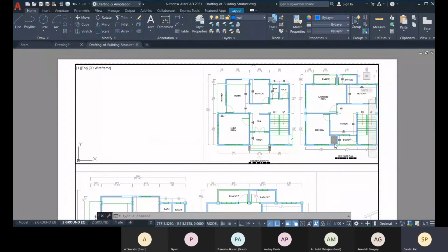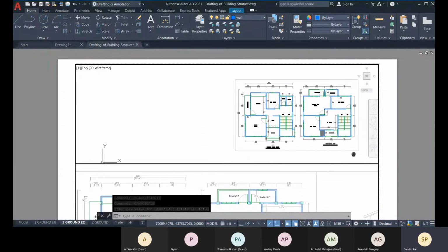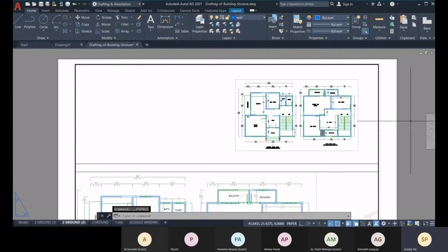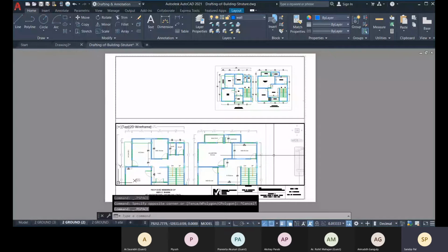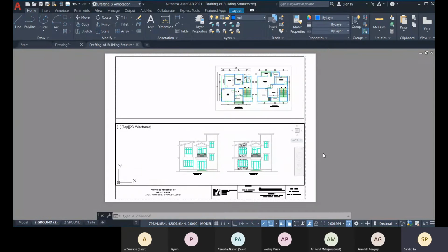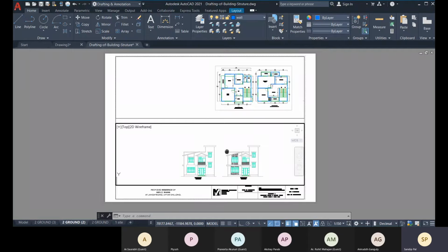This is selected right now, and here you go to this 1 is to 150. Yes, this is right now fit, and you can place it a bit to the side, and lock it with this scale. You double click outside of this, and if you double click inside of this viewport, you can assign this. If you pan it, the scale won't be affected, but if you zoom in or zoom out, the scale will be affected. So this is locked right now.